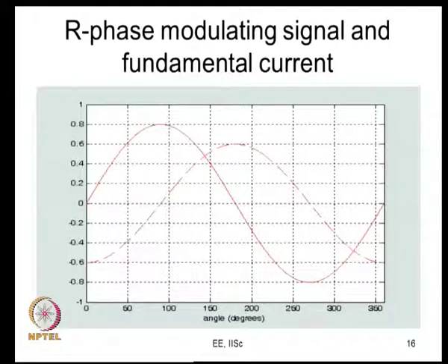What decides the energy loss? It is the DC bus voltage. It is not the fundamental phase voltage, it is the DC bus voltage, and the DC bus voltage is always the same throughout. So, once again what you will have here is a similar kind of energy loss, there is just a phase shift here. This would be your nature of energy loss.